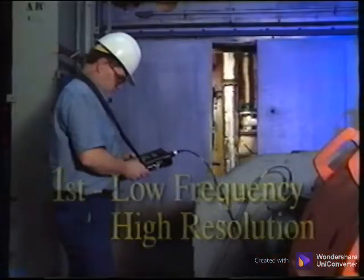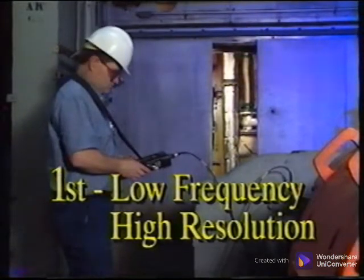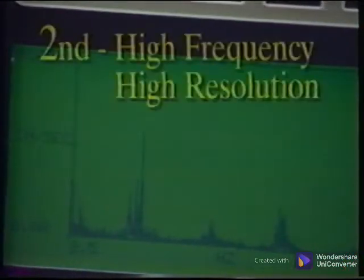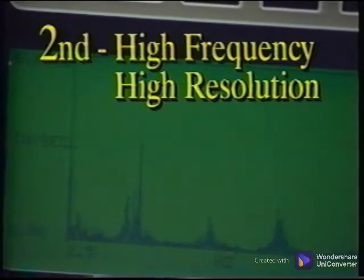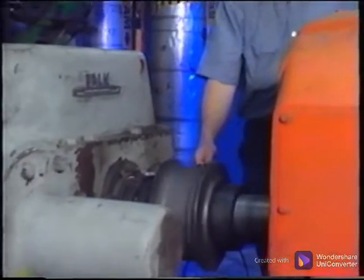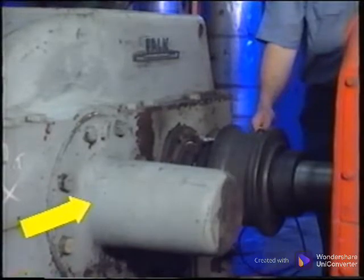1 measurement would be low frequency, high resolution for detection of balance, looseness, misalignment, and bearing problems. The other reading would be very high frequency to 3 or more times the gear mesh frequency with high resolution for determining gear condition. The direction of radial measurements should be in the line of force of the gears, through the center line of the shafts.